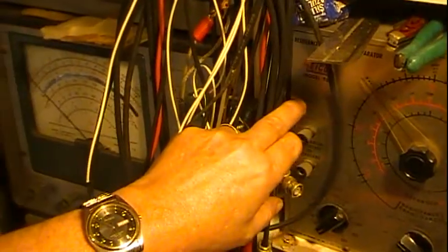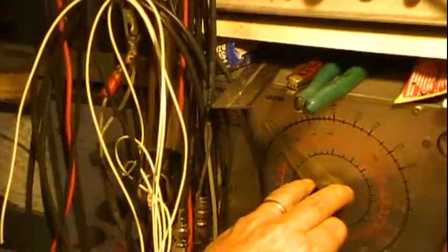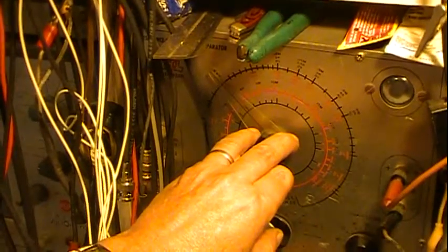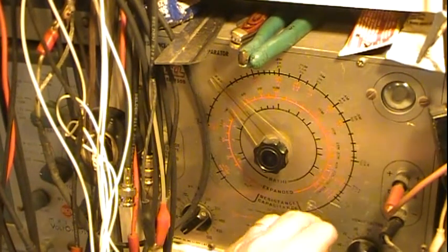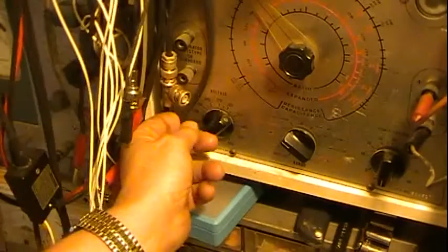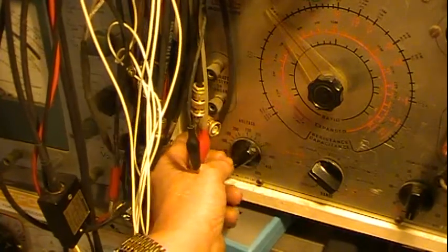Now, here's something. The reason why I picked this one out was they would have been using a tester like this. This is my Coil 950B. You've seen it before, it's a bridge. You not only check for capacitance, but when they did their test, they would also check it for leakage down here by turning the knob to leakage, and this one goes up to over 500 volts.